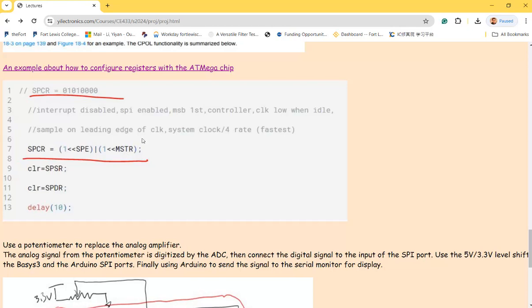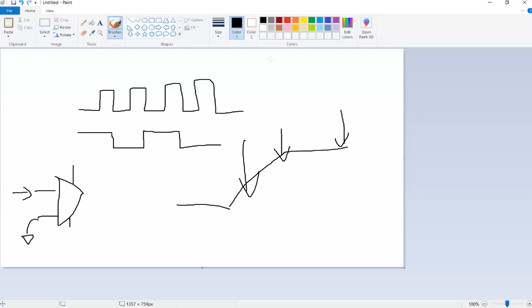on. So in the past, for the PIC microcontrollers with Microchip, they can do the register name and dot. You know what I mean? So, for example, that's the register name A, and dot 1. So 1 could be bit 1 of the register, and you assign a 1 to it, so you can assert that bit in that byte, in that register, with a logic 1. That's the older convention of programming the configuration bits for the registers.